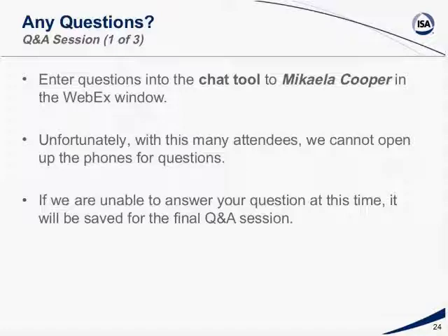The first question comes from Martin, and he says, you speak of a minimum number of alarms. What is a reasonable high number of alarms per unit of time that will not overwhelm an operator? What's considered manageable is 2 alarms per 10 minutes, but your target really needs to be 1 alarm for every 10 minutes.